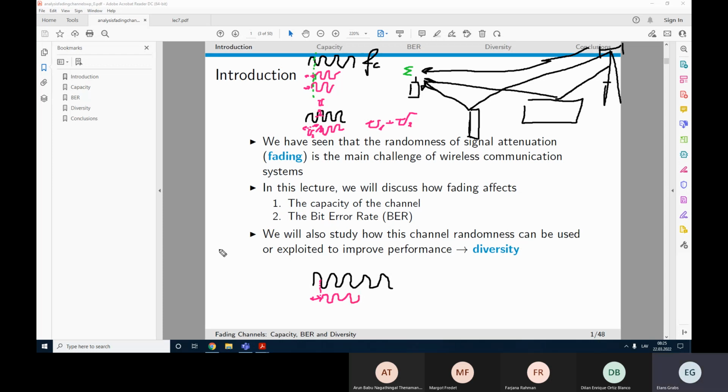I'm not really drawing smoothly here, but the idea is somewhere here. So here the signal is negative, minus U amplitude. Here it is positive, plus U amplitude. So in total, if we use the same notations, here amplitude was U1 and here amplitude was U2, which are not exactly the same. And usually this U2 is smaller than that of the direct path because, as I said, we lose some energy during this reflection or diffraction process.